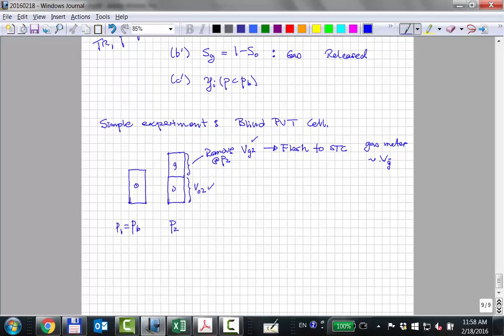But basically, we use a gas meter here. That gives us approximately the number of moles of gas that have been removed. When you flash it, there might be some small amount of flashed oil. This is usually ignored or not measured very accurately, but it may be there. But this surface gas converted to surface volume of gas and the surface moles of gas. If you add these two together, you get the moles of gas removed.